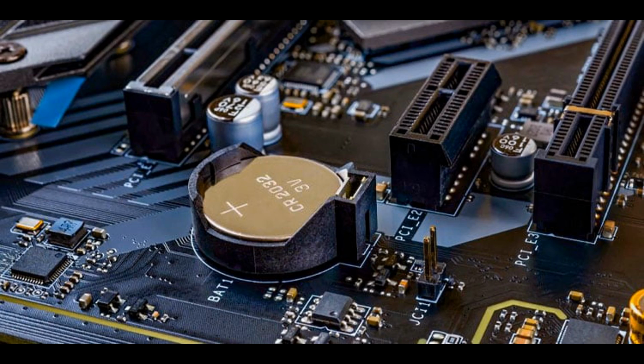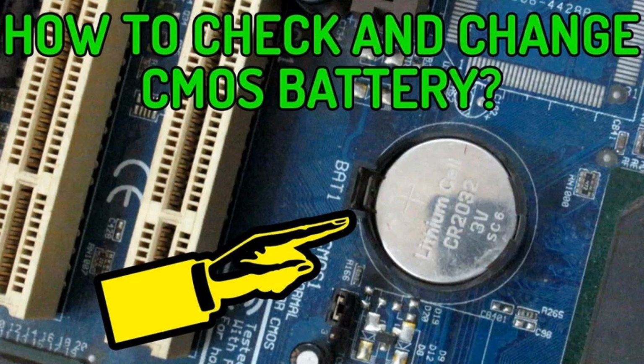The substrate is doped to create either an N-type or P-type semiconductor material, depending on the desired characteristics of the MOSFET. Source and drain. These are the two terminals through which current flows in the MOSFET. The source is where current enters the device, while the drain is where it exits. The source and drain regions are heavily doped to facilitate the flow of charge carriers, electrons, or holes.